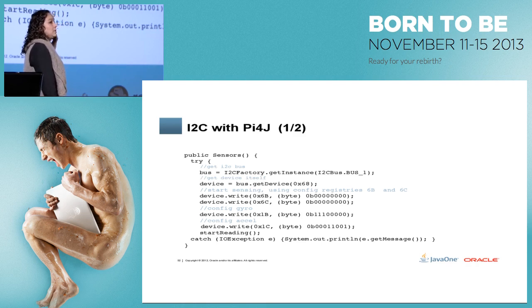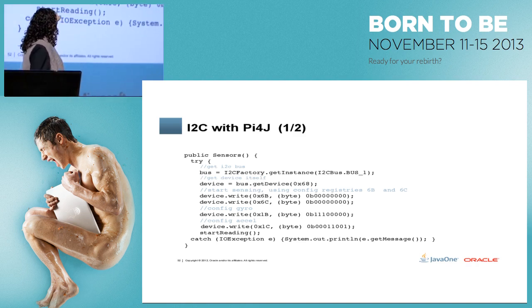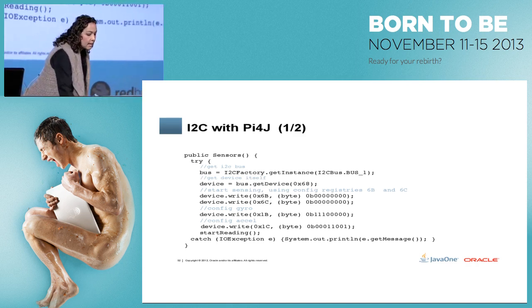So the problem was that this particular board is in sleep mode. So you have to wake it up and say, hey, I need to start reading. Those are the two lines. Start sensing: in registry 6B and 6C, you need to reset to 0 so it actually starts the reading. Otherwise, you won't get anything.